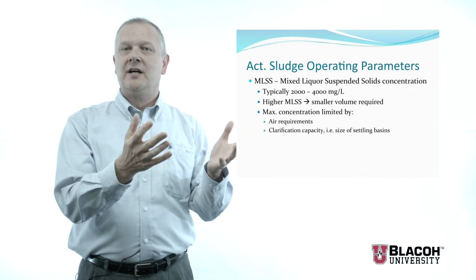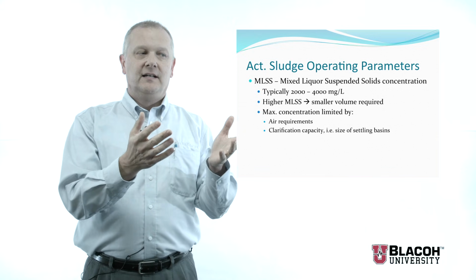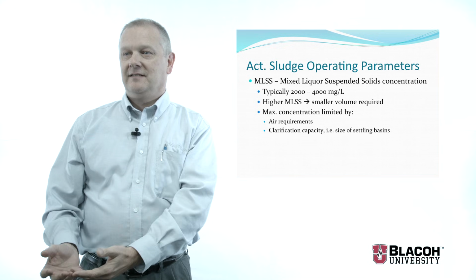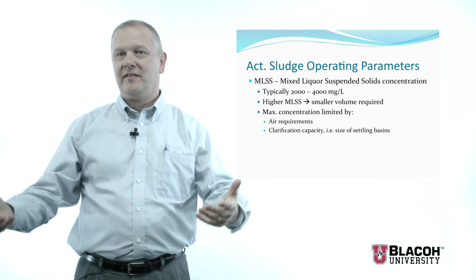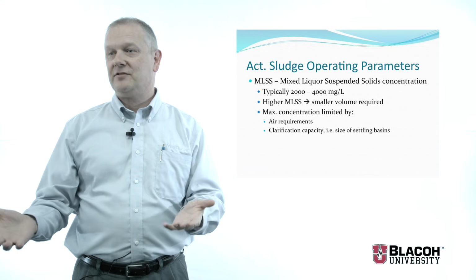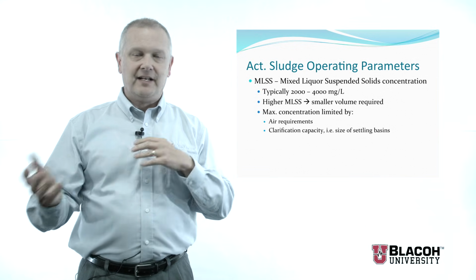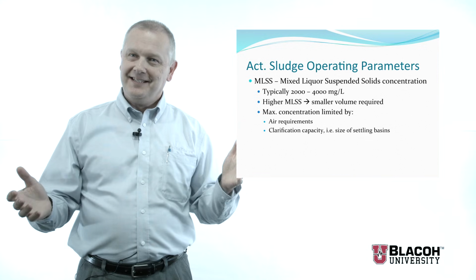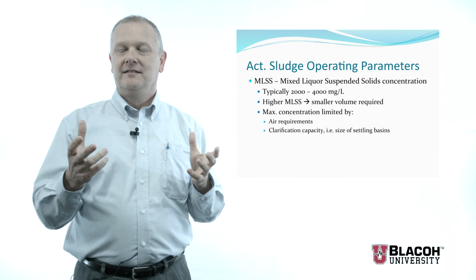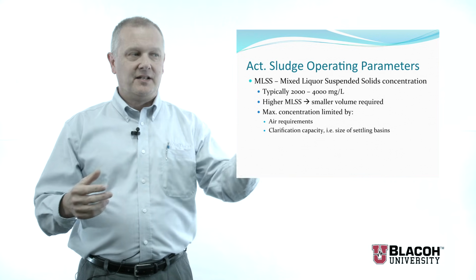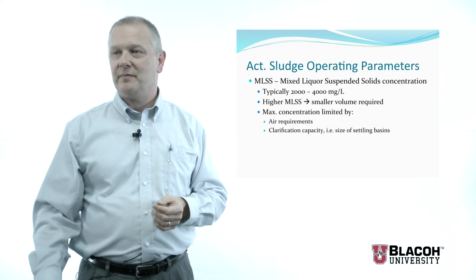If you have too high a concentration of solids, it will not settle as rapidly, and you'll need immense clarifiers to try and settle very, very highly concentrated solids. And so that limits the concentration that you can build this aeration basin concentration up to. And like I said, typically it's between 2,000 and 4,000 milligrams per liter.